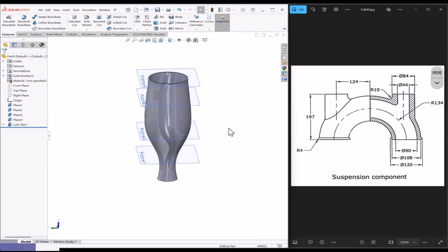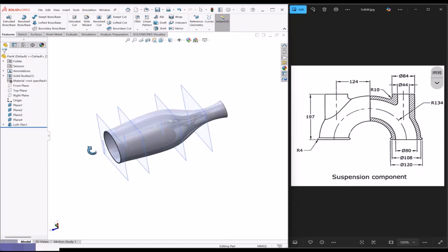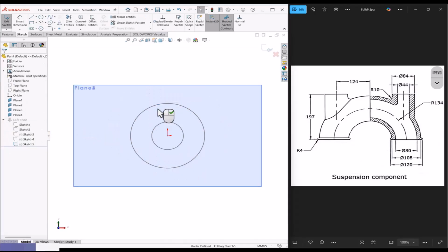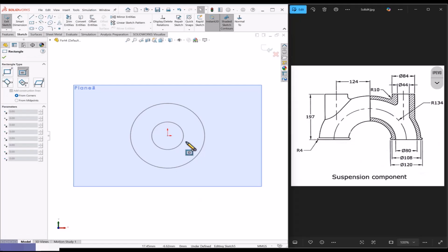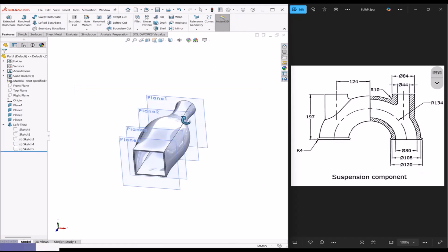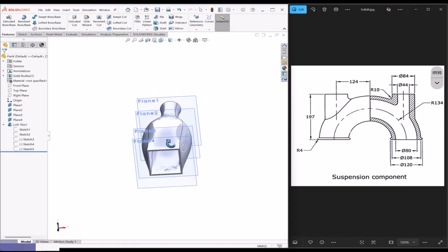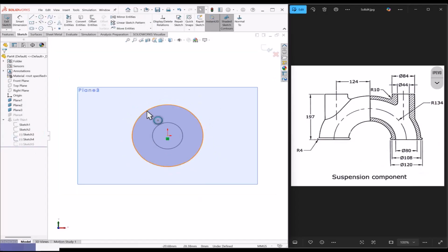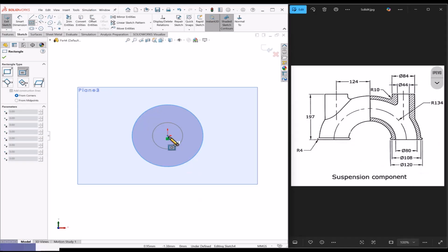Next, we'll see. Right now I used a circle. Maybe you want to use a rectangle or something. Maybe you feel, I want to change the base to a rectangular shape. So let's edit it within this sketch. We'll use a center rectangle. Let's take the base to be a little square form. Exit. See here, the base has been changed to a square. Or maybe I want to change the update to the sketch also. Let me first create this and then delete that circle.